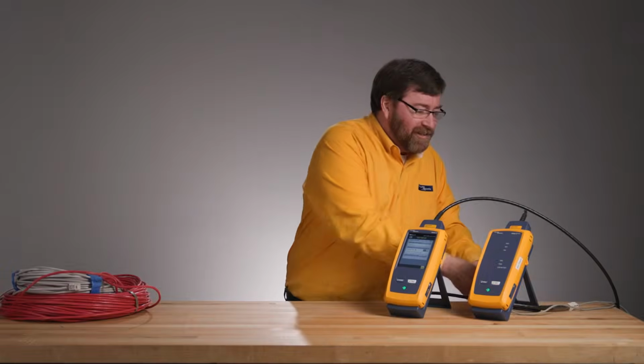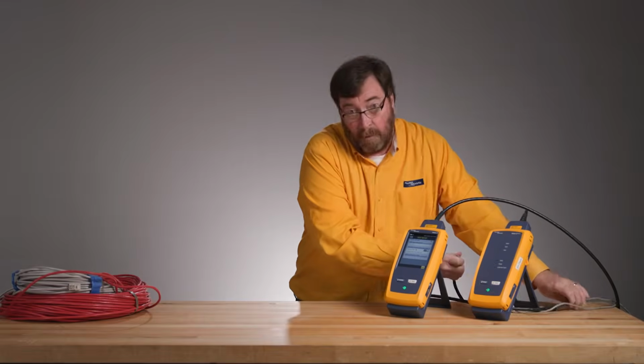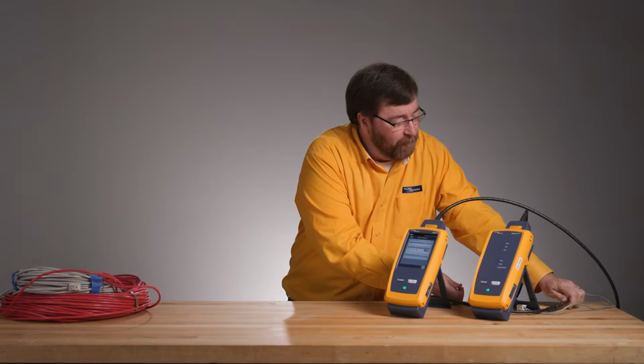We're going to create our extended reach limit here by putting together a couple of different pieces of cable. You have a device that's more than 100 meters away, more than 90 meters from the closet, plus 10 meters for patch cords. Somebody said, I have a sensor on the roof. The sensor on the roof tells me if the fan is running. How do I get up there?